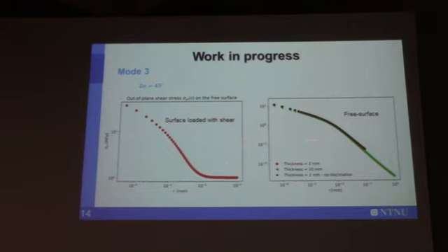At the free surface the out-of-plane shear stress component should be 0 from the boundary conditions, while we obtained by finite element modeling an increase near the V-notch tip. To understand this, we loaded the surface with shear and we saw that this behavior still happens.